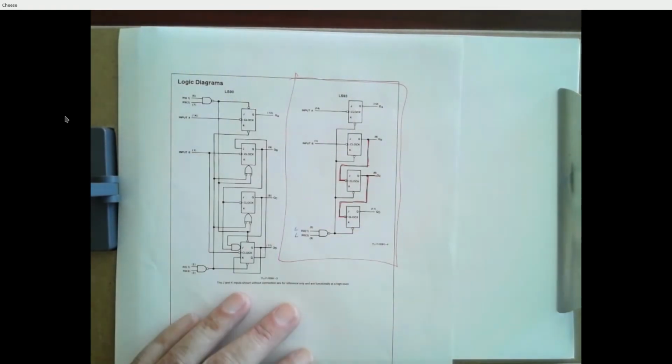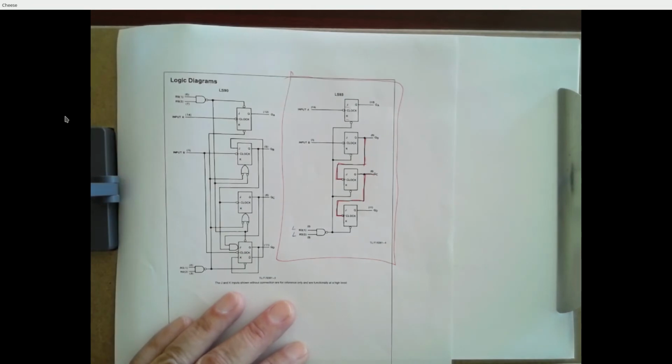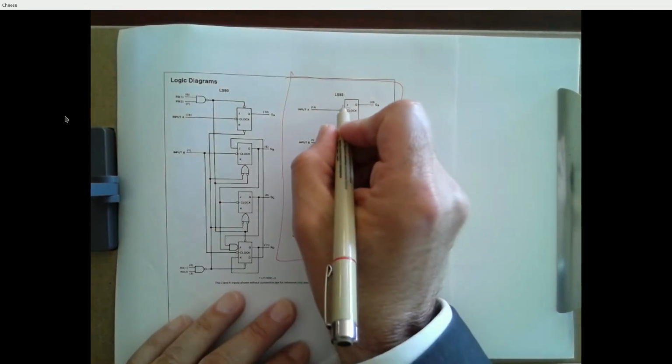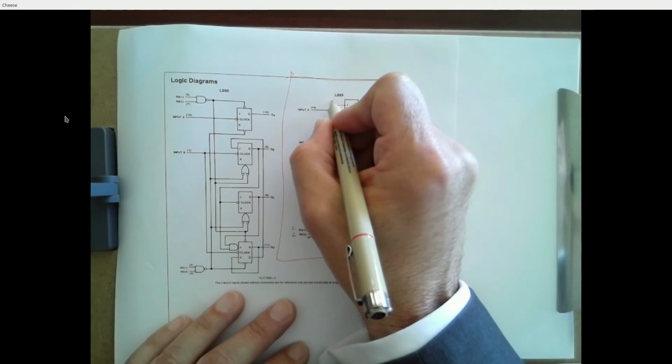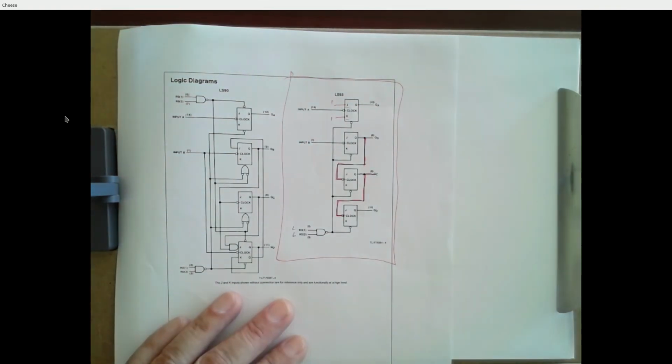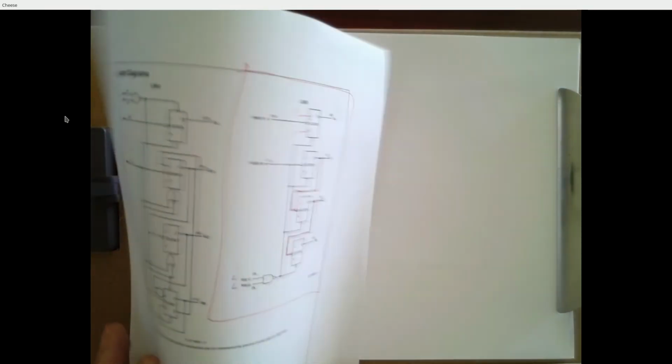So what kind of flip-flops are these? JK, right? There's a J, there's a K. It's not showing us what the values for J and K are. There's no inputs here, but they're effectively being treated as if they were both 1. In general, when you have an unconnected input in a picture like that, we can be pretty sure that it's a 1.